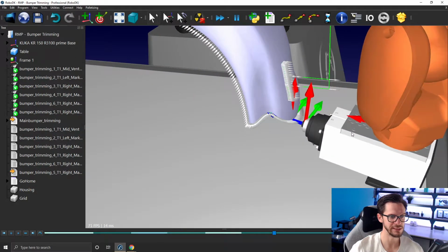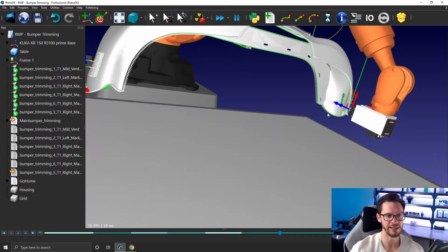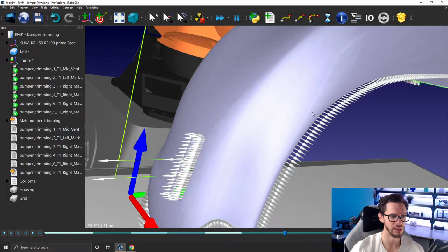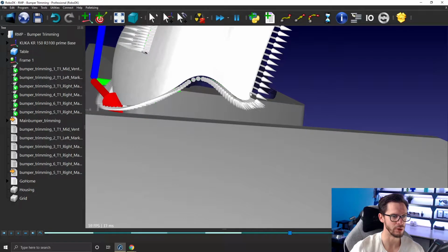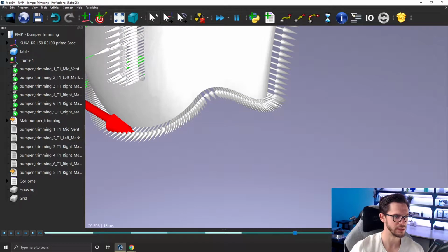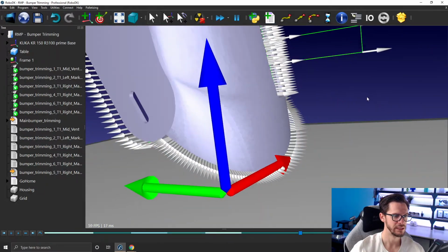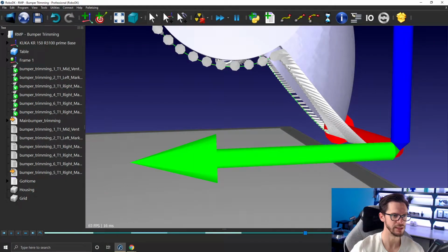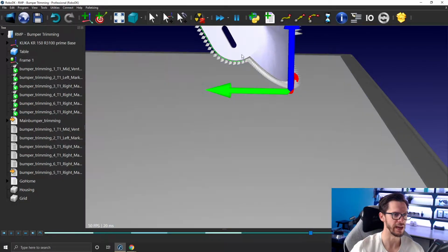The cool thing with NC files is that CAM software, this is their job, so they're good at creating paths and profiles like that. You can see that the points are pretty much always equally distanced, and if you have a more specific curve to follow, the density of points will increase in certain places like that. Here it will follow the corner. We'll make sure that the radius of the tool is considered in how the path is built.